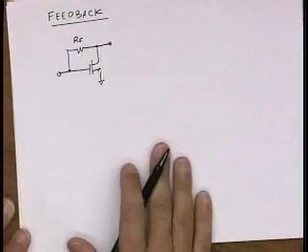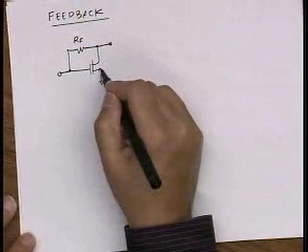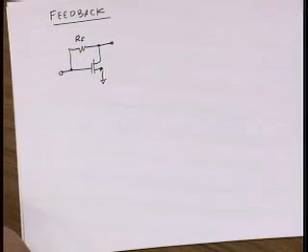Okay, so quick question. Why is this a good example for analyzing feedback? Or actually, what's particularly difficult about this kind of amplifier? Let's say as opposed to an op-amp with shunt feedback. In fact, is this a feedback amplifier? I mean, the gain and the input and output impedance are finite, so you have to consider the loading. Sure, yeah, loading is going to be very important in this amplifier. Anything else? Any other, let's say, non-ideal property of this amplifier?